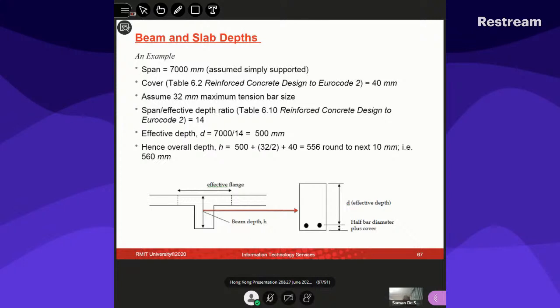So you can quickly find a floor plate framing, which is pretty much a decision making process, and then you do the calculations to optimize, computer analysis and things like that. But you have to have the framing plan to do that. Otherwise, you don't know what the span of the beam is, which direction the beam is spanning, between which wall to which wall. You have no idea.